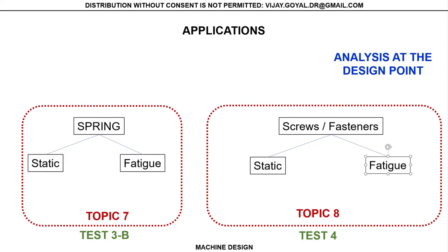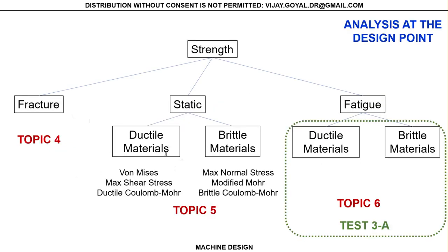It just goes there, but then I keep moving. So now this is more an oscillation problem than a constant applied load problem. There are cases in which you might see that this pencil might fail in static before it fails in fatigue, and vice versa, that can also happen. So you have to always check for both. That's why you see that for all the problems I'm suggesting, we do static, we do fatigue. We do static in strength, and we do fatigue in strength. This is where the money is.